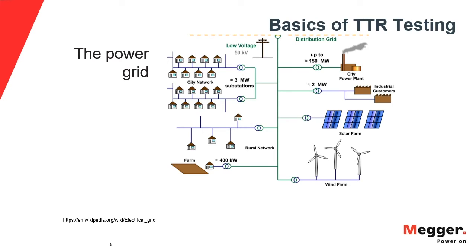It's one of the very basic functions of a transformer, and being so, we want to make sure that the transformer is complying with that relationship between the voltages of those two circuits in the simplest case. So that's what the TTR test is going to do for us when we measure it on any given transformer.